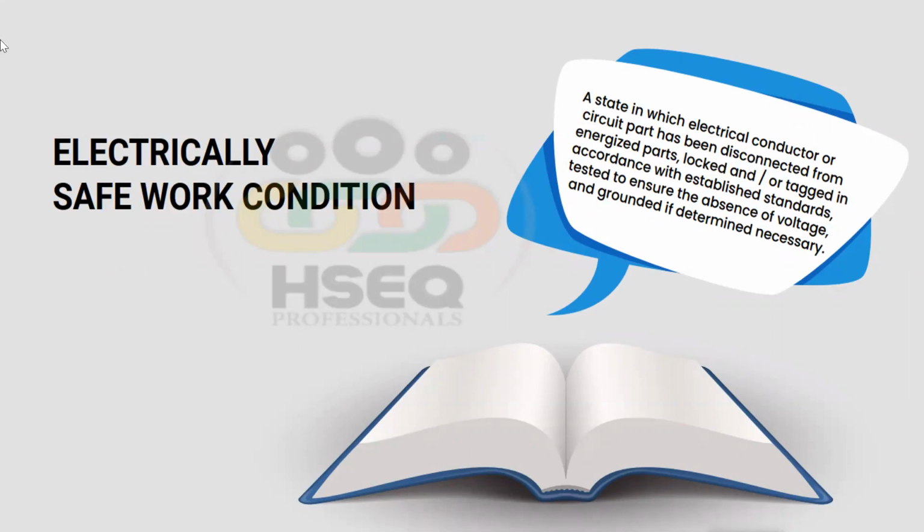Moving towards the electrically safe work condition: a state in which an electrical conductor or circuit part has been disconnected from the energized part. Normally people think that once they have done this first thing, the equipment has been put into an electrically safe work condition. This is wrong.